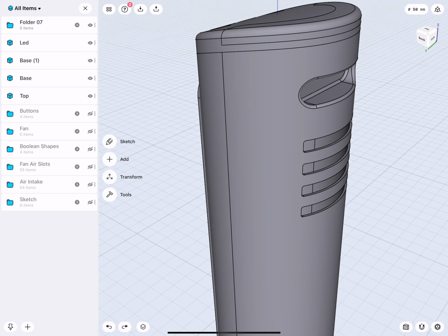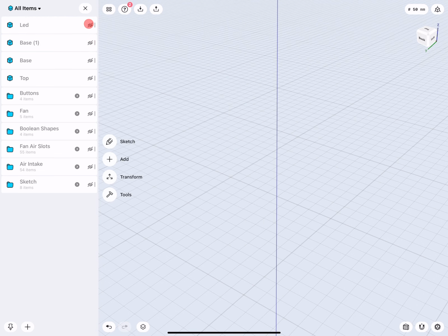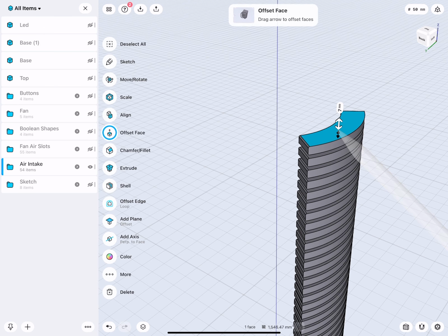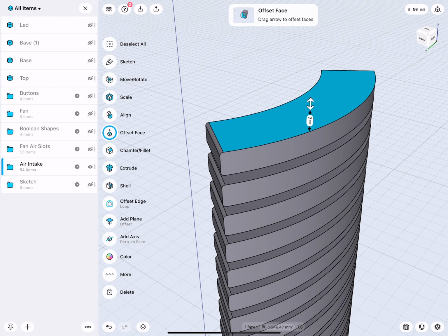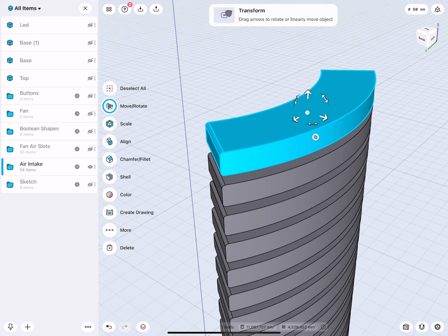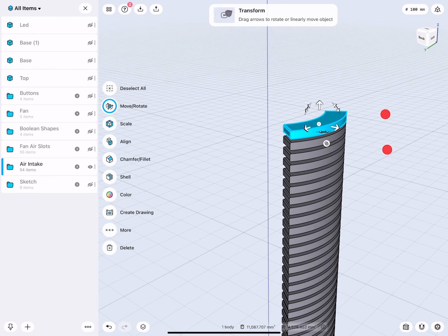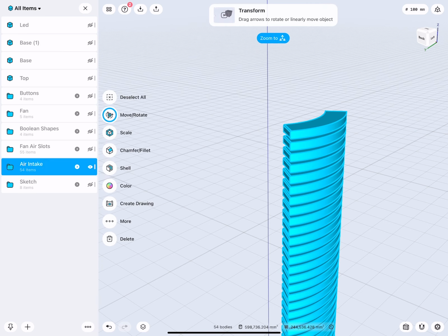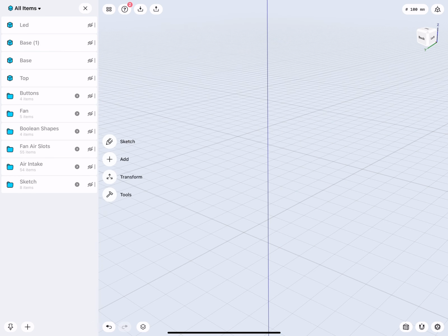Then it's actually much easier also to work with copies. And I, for example, in this folder, consumed the solid objects. That is why, for example, here I still have the original objects. So if I need to make a modification, I can remove everything, select this one, modify it, and then multiply everything again and do my Boolean cut with the selection of this folder.